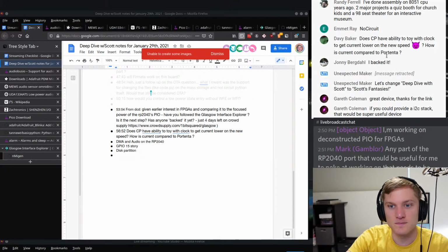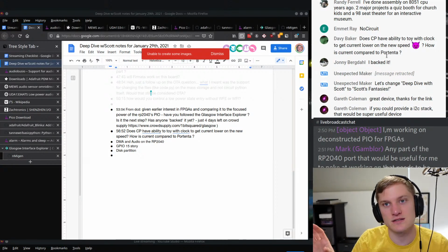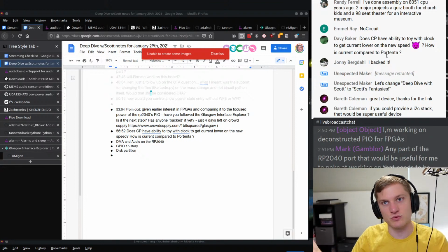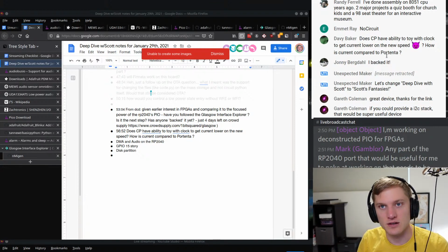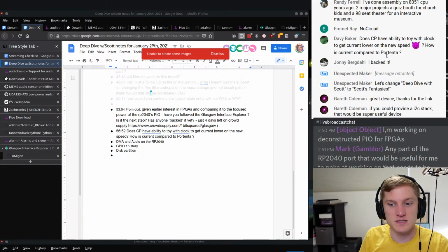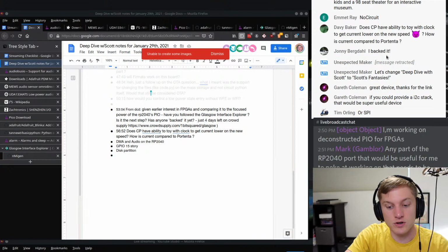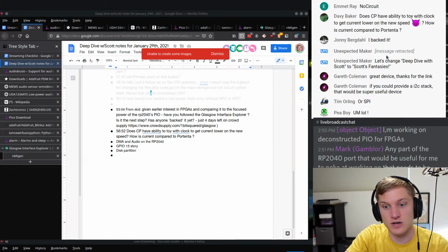What happens when you try to design APIs that work across boards is you really have to simplify them. Like with our sleep state stuff, it's basically you're on, you're running, you're idle, or if you're in light sleep, you try to turn off as much as you can. And if you're in deep sleep, you turn everything off, including your RAM.